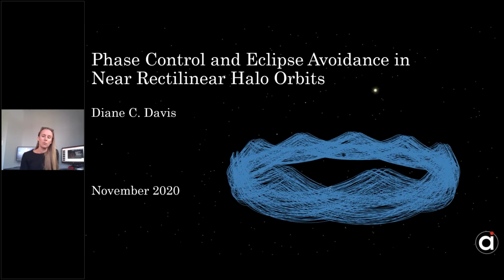Now, for power and thermal reasons, the Gateway wants to avoid eclipses that are longer than 90 minutes. So if you're clever, you can select and align a near rectilinear halo orbit so that it naturally avoids eclipses that are long due to the Earth's shadow. Once we've designed a baseline that avoids these eclipses, we need a strategy that keeps us in an eclipse-free phase near this baseline. So my goal today is to discuss eclipse behavior in the baseline NRHO, and then also discuss an orbit maintenance strategy that helps us achieve these goals in the presence of operational errors.